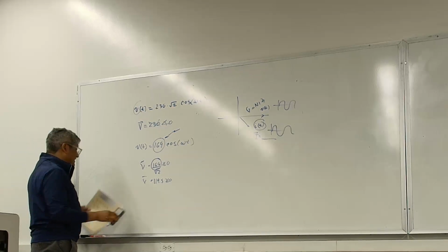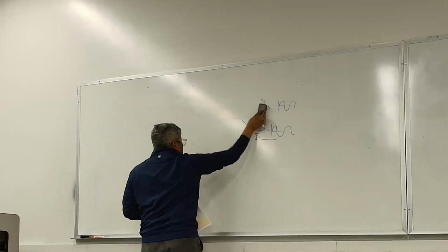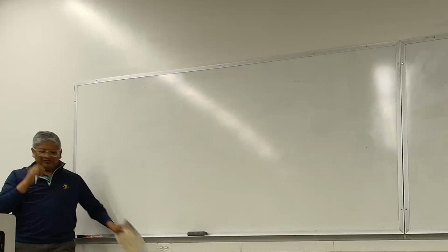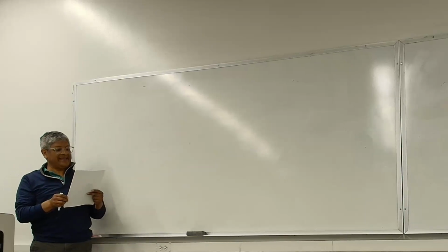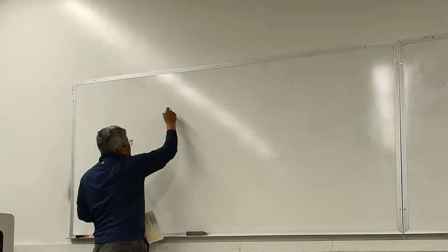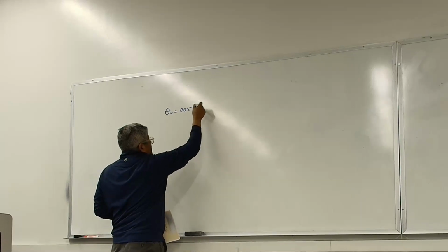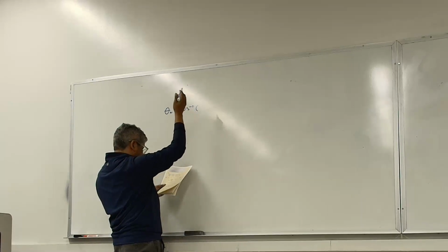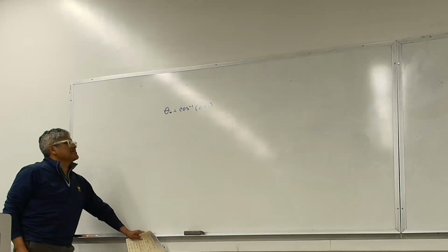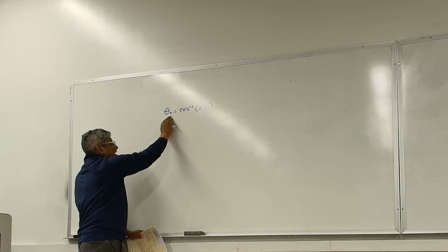The other one was on the power factor. When I was asking for the capacity, I think this was the one. Most people were able to find the new angle, which was cosine inverse of the new power factor that they give you, I think it was 0.8 something, say 0.85, right? I had quite a few people struggling with this, finding the angle.